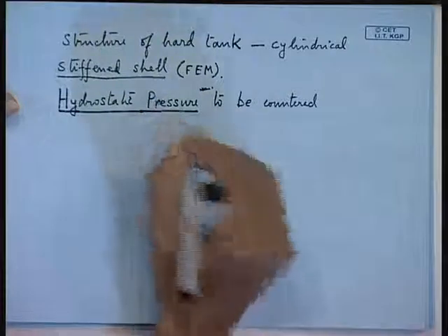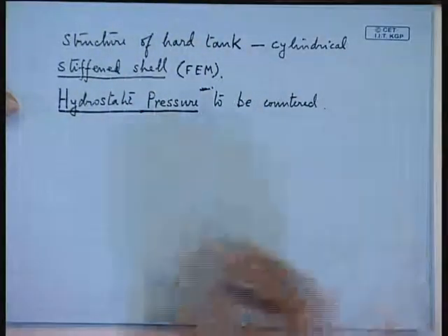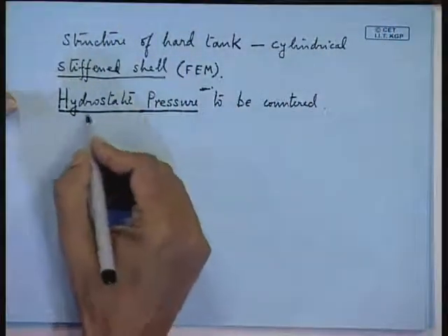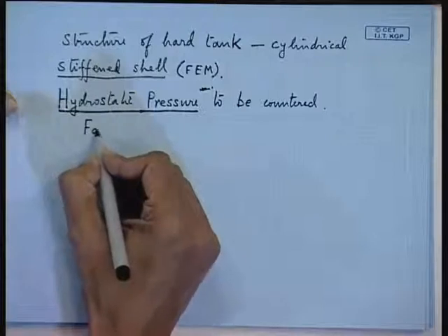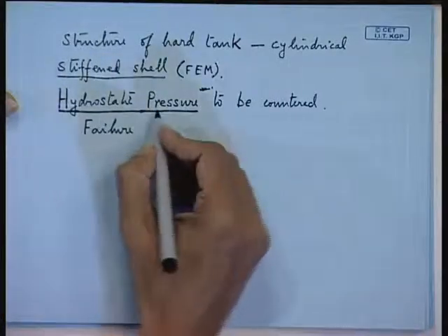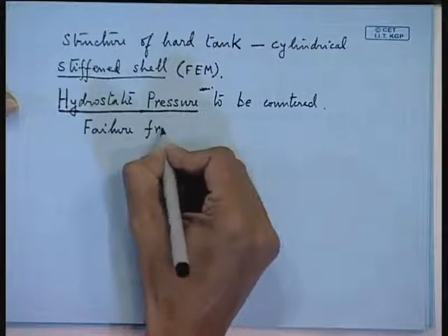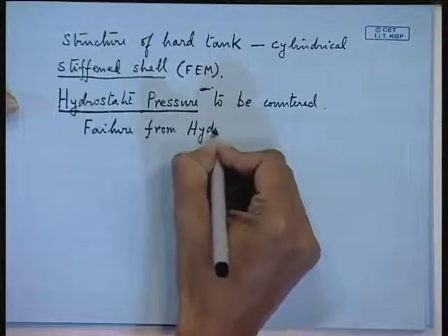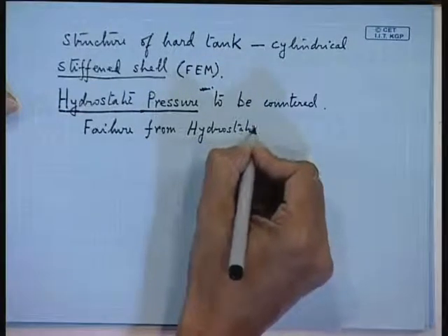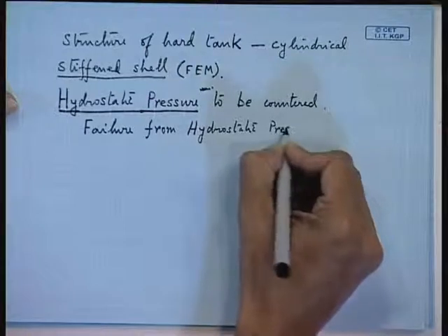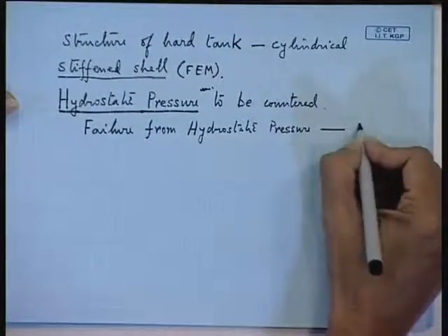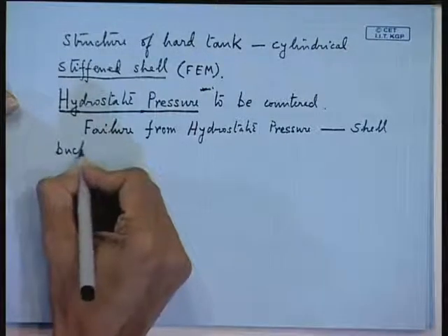So, for your structural analysis, what are the failure modes that you have? The structural analysis is based on your failure modes. Failure modes will be mostly because of failure from hydrostatic pressure. So, you have to do shell buckling analysis.